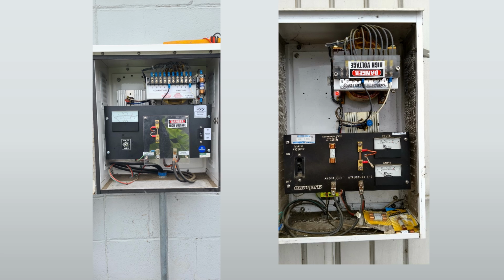Here's our rectifying unit. This is our transformer out in the open. Got our diodes. You can do a spare fuse, hook up on that one. Spare fuses are present, so this system was probably tripping quite a bit. Probably had some other issues going on. Yeah, that can be another indication of issues with the rectifier, is several discarded fuses existing in the cabinet once you open it.